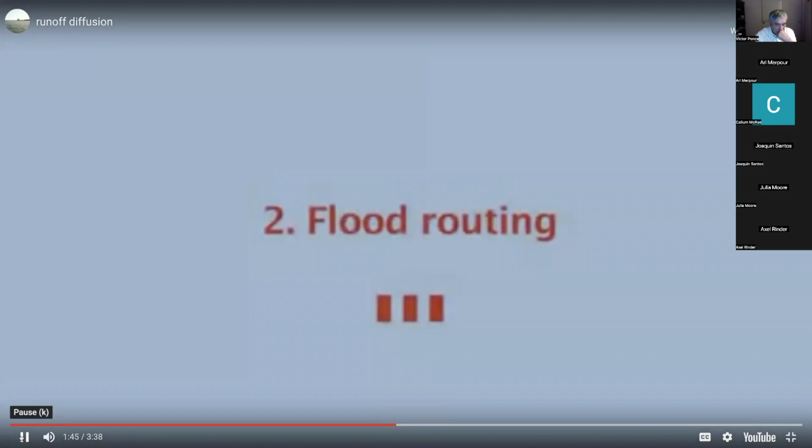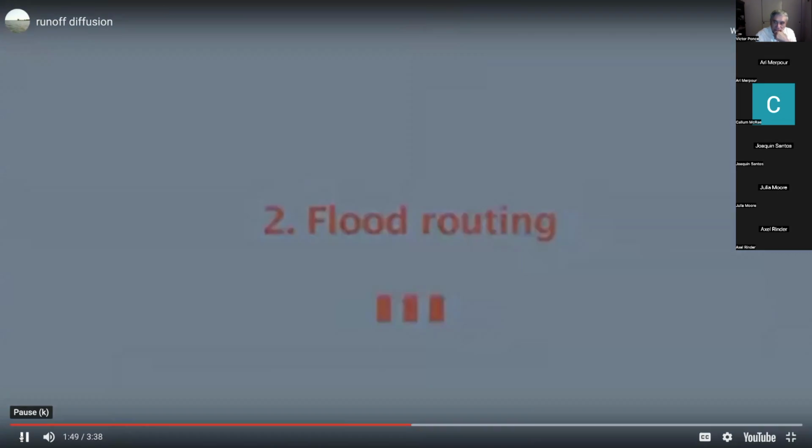Diffusion causes spreading of the flows, increasing the chances for infiltration and reducing runoff peaks and volumes. Flood discharges depend on the prevailing slope, which in turn depends primarily on the watershed or basin size, and secondarily on the stream or river cross-sectional characteristics. The purpose of flood routing is to calculate the amount of runoff diffusion.